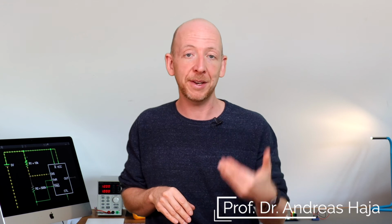In this video we have looked at Kirchhoff's second rule, which is also called the loop rule. And just like with Kirchhoff's first rule, it is based on a conservation law, which in this case describes the conservation of energy in a circuit. And one consequence of energy conservation is that the sum of the partial voltages in a circuit with the same start and end point must equal 0. And in practice, this means that the loop rule can be used to determine unknown voltages or to calculate the total resistance of components connected in series, which also exploits the current equality in an unbranched circuit. And there are many more applications for this rule, which we will discuss in future videos.